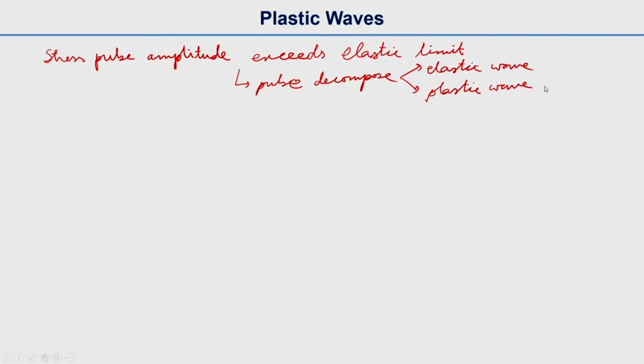We know that when a material is stretched beyond a limit, that is the elastic limit, plastic deformation happens to the material. Similarly in this case, when we have dynamic loading and the stress pulse amplitude exceeds the elastic limit, then this wave will be decomposed into an elastic component and a plastic component.